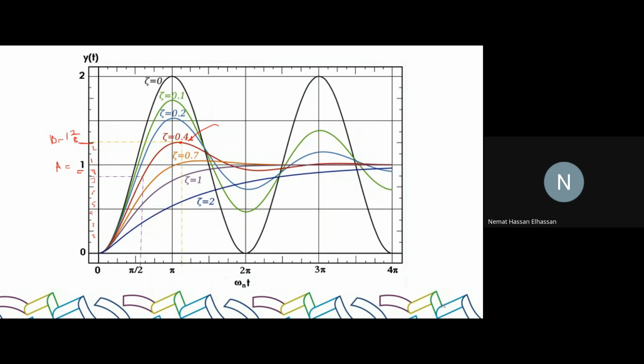So that means my percentage overshoot is equal to 1 and 2/8 minus 1, divided by 1, which is equal to 2 over 8. 2 over 8 is how much? It's 1/4, which in percentage is 25%. Make sense? But now, how to write it?